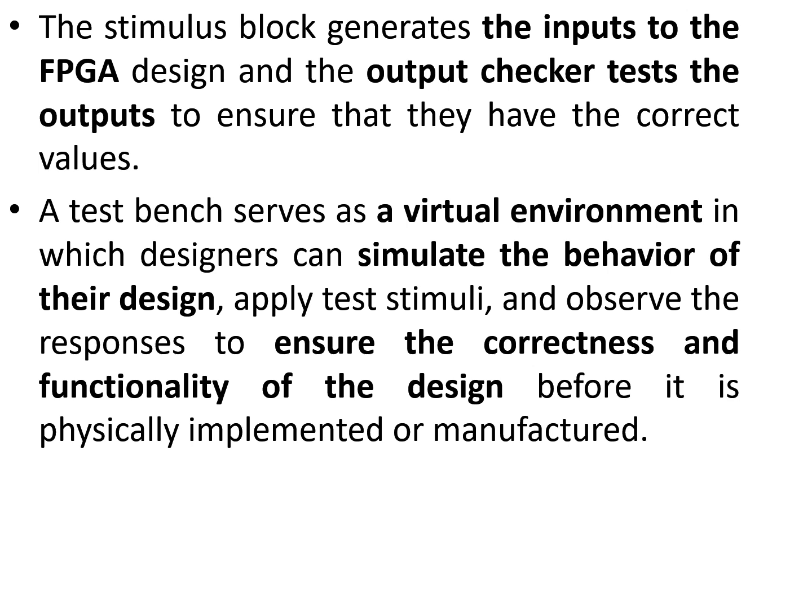The stimulus block generates the inputs to the FPGA design and the output checker tests the outputs to ensure that they have the correct values. A test bench serves as a virtual environment in which designers can simulate the behavior of their design, apply test stimuli, and also observe the responses to ensure the correctness and functionality of the design before it is physically implemented or manufactured.